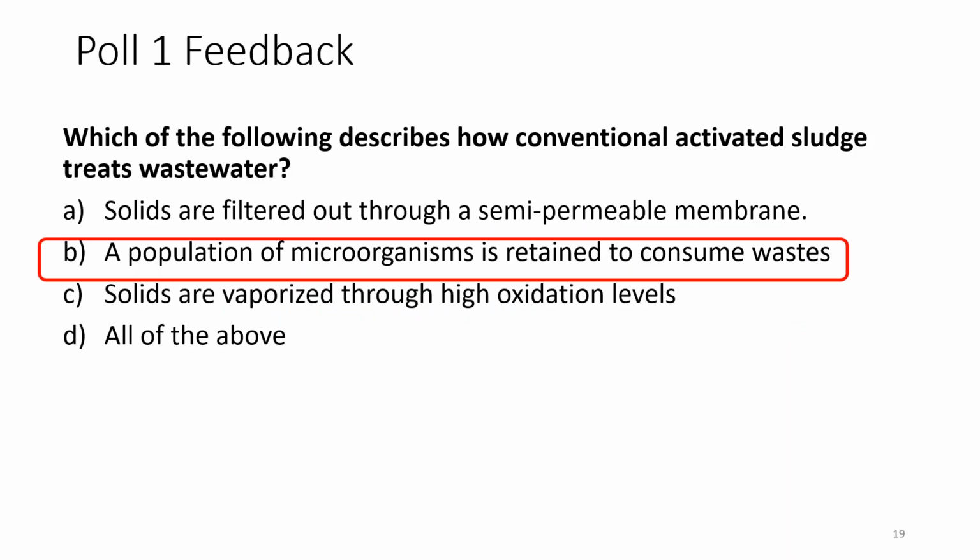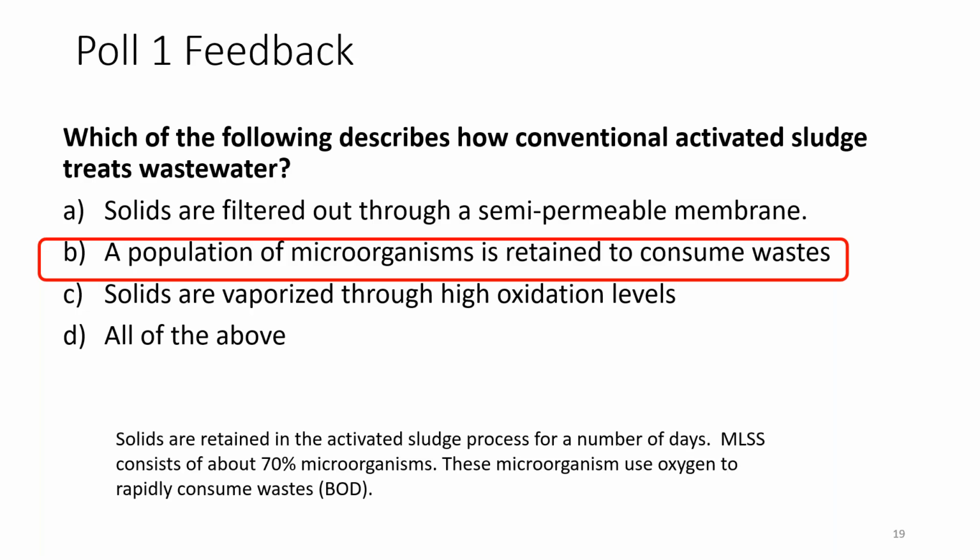We're collecting those microorganisms in the secondary clarifier, and we're recycling them back into the aeration tank, and those microorganisms are hungry and they consume that BOD that's coming in. And of course, we're aerating too. We're creating the perfect environment for those incoming wastes to be consumed quickly. The solids that settle in the secondary clarifier consist of about 70% microorganisms, and the microorganisms use that oxygen as they're consuming the waste.